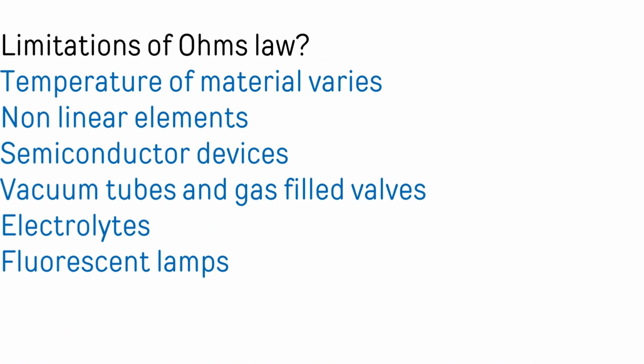Limitations of Ohm's law. If the temperature of the material varies, Ohm's law is not applicable. For non-linear elements, Ohm's law is not applicable. For semiconductor devices, Ohm's law is not applicable. For vacuum tubes and gas-filled valves, Ohm's law is not applicable. For electrolytes, Ohm's law is not applicable. And for fluorescent lamps, Ohm's law is not applicable.